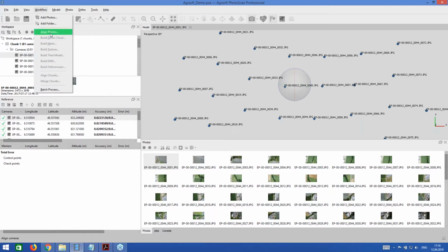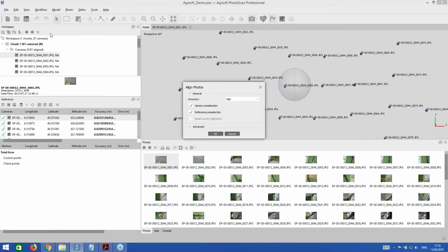The algorithm has several parameters. Accuracy parameter controls the quality of aerial triangulation, while pre-selection settings allow to reduce processing time. The values we now see on the screen are the recommended ones for a typical aerial dataset, the one you will export from eMotion. Let me skip detailed discussion of the parameters not to overwhelm today's audience with information at